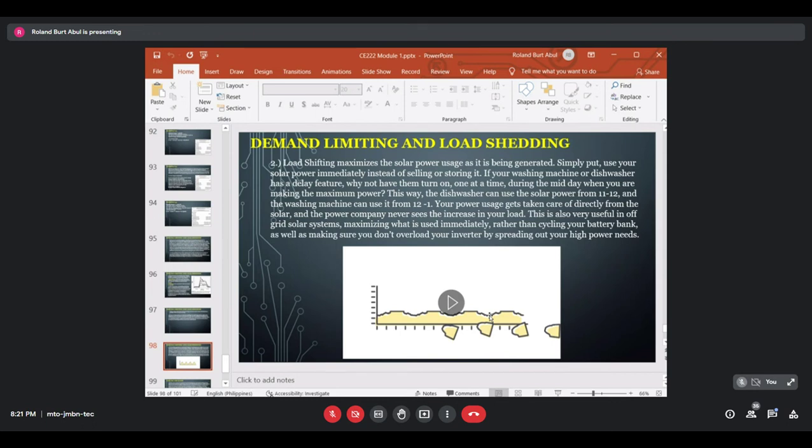Okay, so energy storage and alternate sources of energy can also be used to reduce demand peaks, a technique called peak shaving. So first example, in an ice storage system, ice is made by a building's air conditioning system at night when demands are low. The stored ice is then melted to chill water for cooling the building when air conditioning demand peaks in the afternoon. Ice storage has the added benefit of requiring reduced air conditioning capacity. A cogeneration system that produces electricity from waste process heating or by consuming fossil fuels can be used to limit demand.